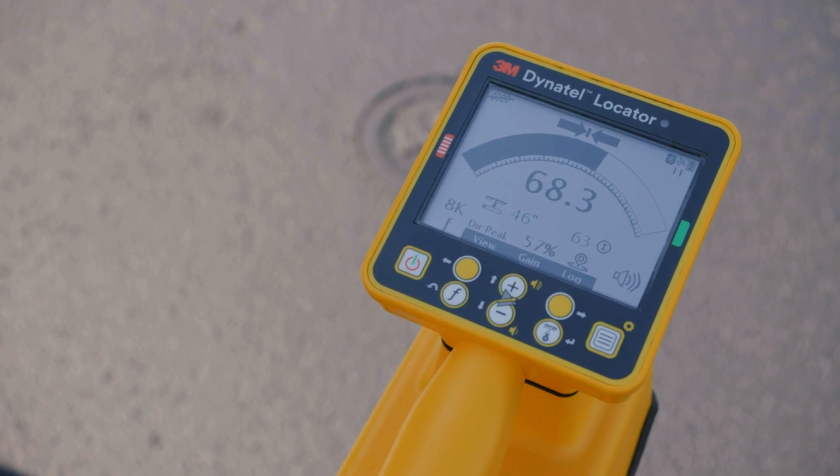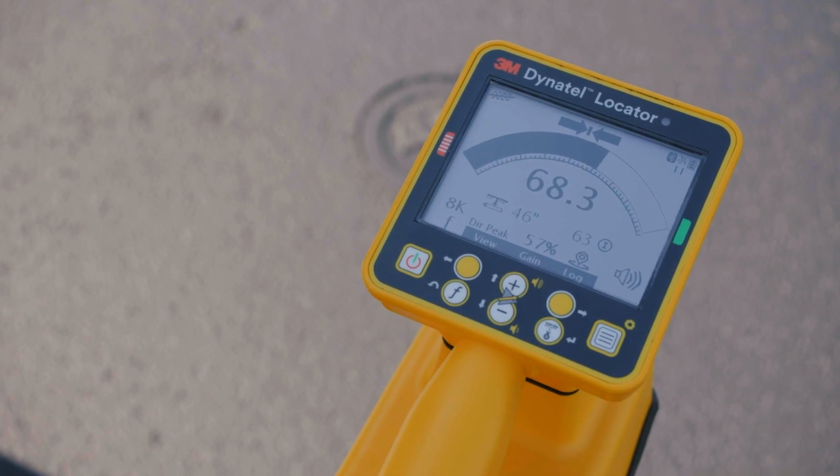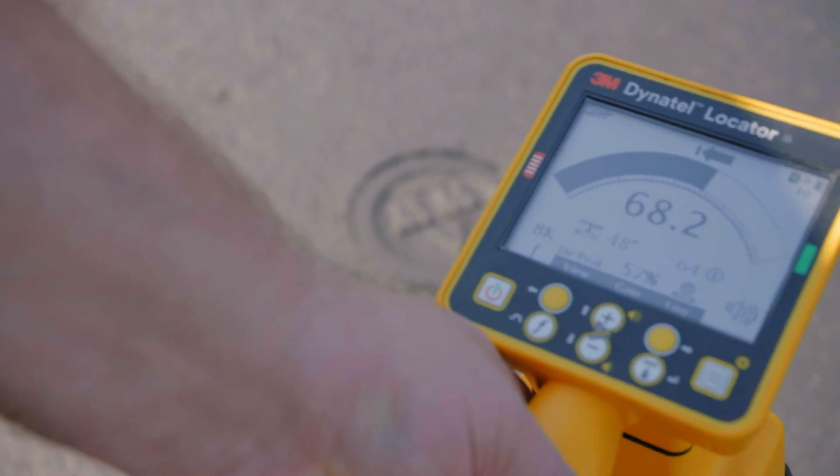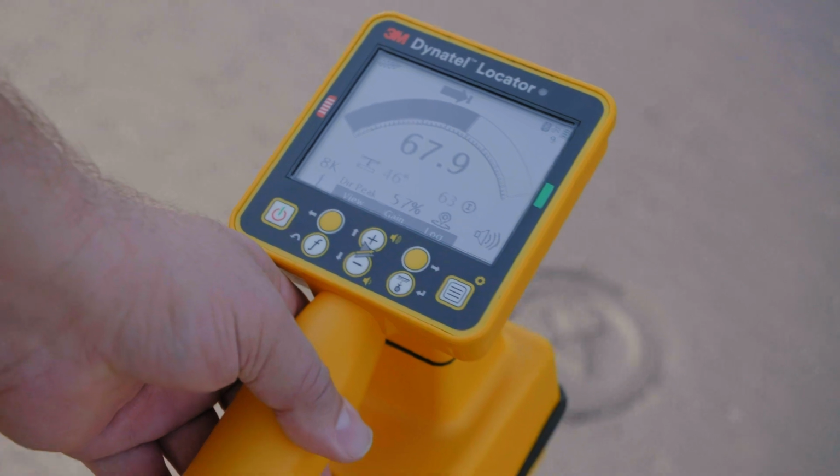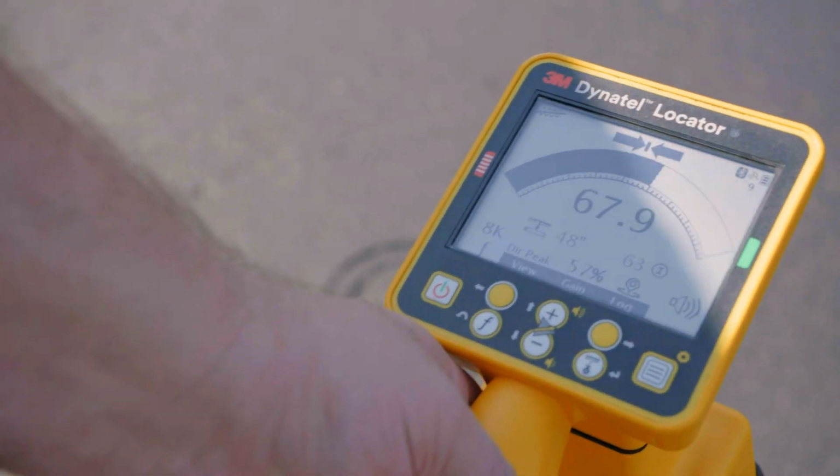The numerical signal strength in the middle of the locate screen indicates the actual strength of the transmitted signal that is reaching the receiver. The point at which this numerical signal is the highest value indicates the center of the electromagnetic field or the target conductor. The bar graph should display the least amount of signal when the receiver is off target path and the most amount of signal when over the target path.